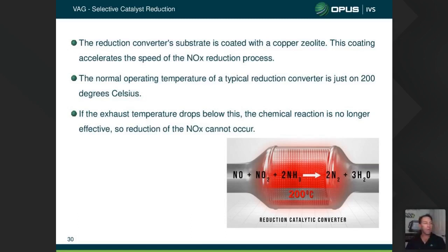So I think a catalytic converter operates around 350 to 600 degrees Celsius. It's very, very effective. Over about 600 to 800 degrees, your cat converters really start to melt. So the temperature for a petrol catalytic converter has to be much higher. Great thing about diesels, at 200 degrees Celsius these things work, which is just as well because diesel exhaust temperatures are a lot lower.